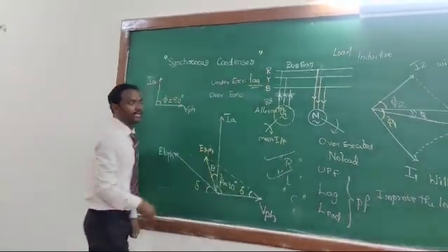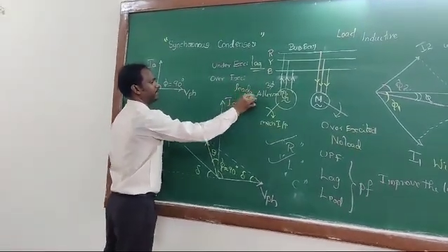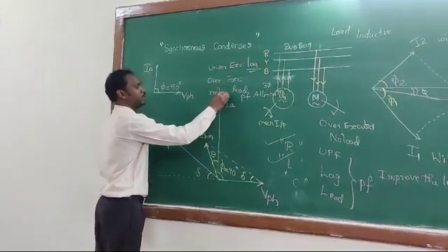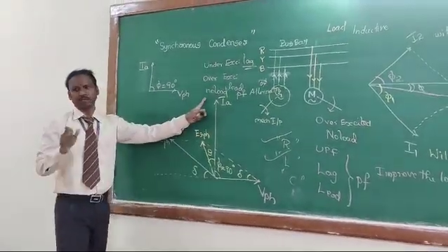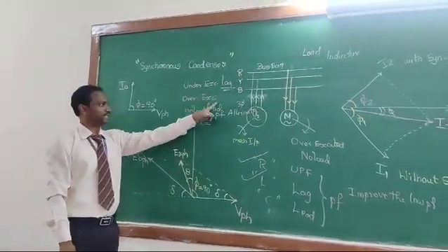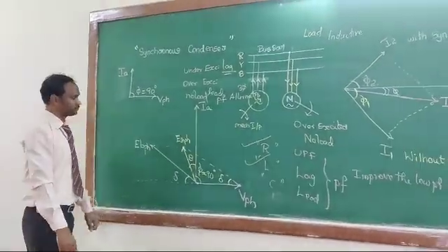Under excitation gives a lagging power factor and over excitation gives a leading power factor, that is, under no load condition. If the synchronous motor is under no load and the excitation is over excitation, then it shows a leading power factor.